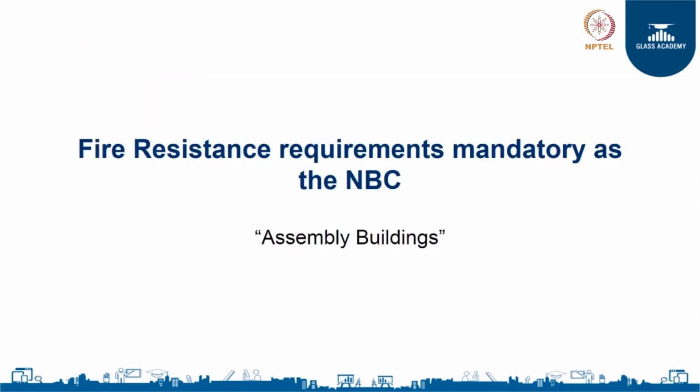Next, I am going to be talking about the fire resistance requirements in assembly buildings. Assembly buildings are the type of buildings where you have a lot of people gathering. You can take the examples of theatres or open theatres, or a marriage auditorium. There are so many examples where a lot of people gather, and if you look at the National Building Code, it says if more than 500 people are gathered at a place, it becomes an assembly building.